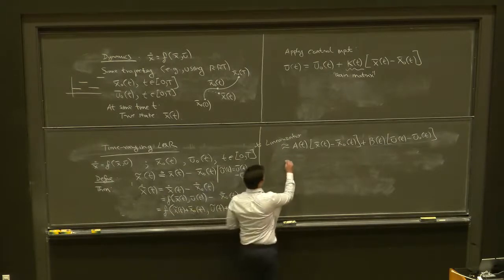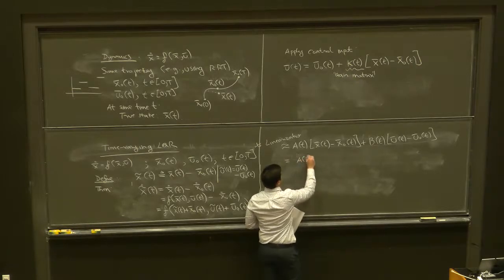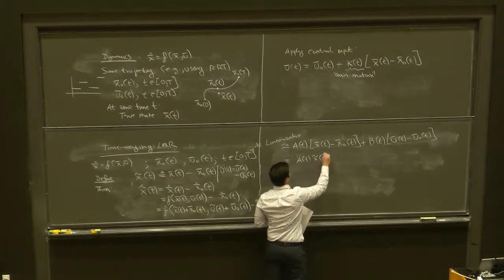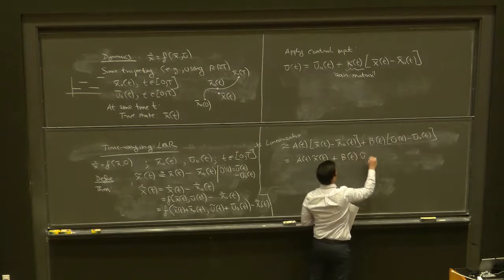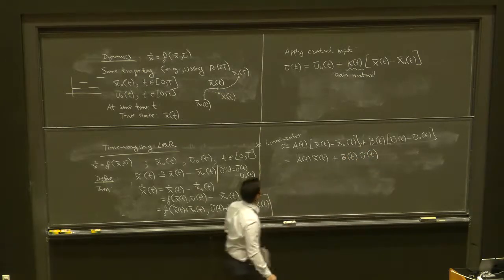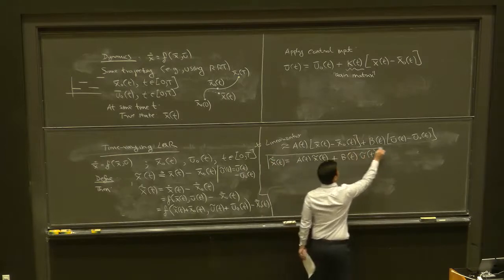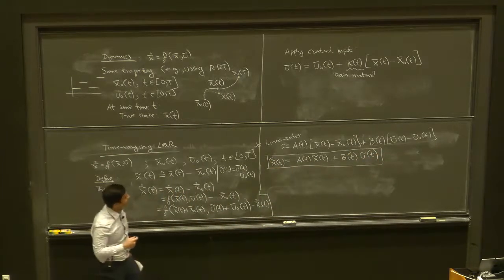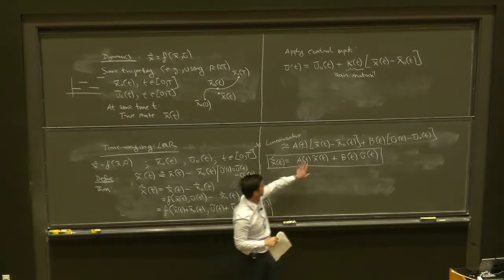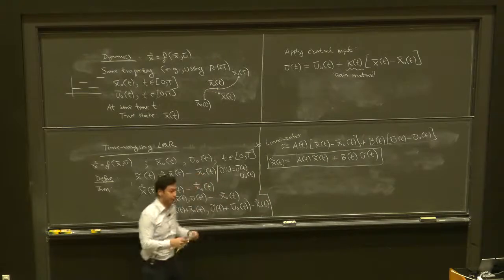So I can write this more compactly then. x minus x0 is x tilde, and this is u tilde, and this is x tilde dot at time t. All right, so essentially the same as our previous discussion of LQR, just with everything here being time varying because we're trying to track a trajectory.